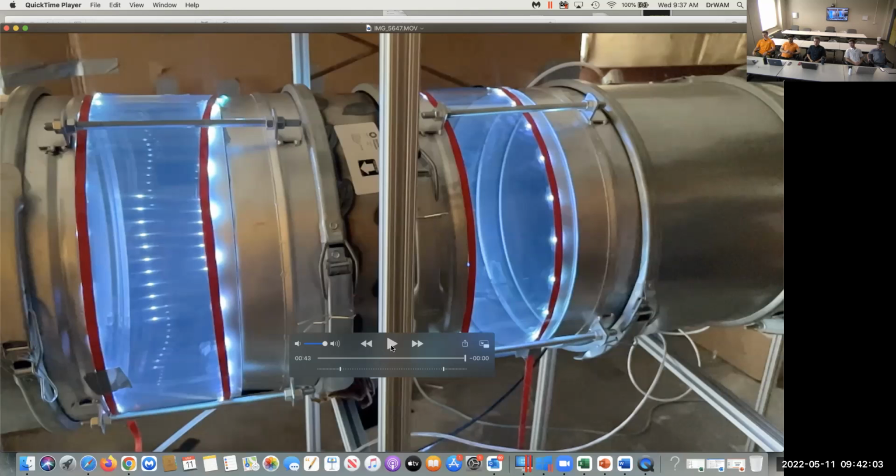And in that instance, am I getting a good mixing across the complete duct section, especially if that duct is 3 foot or 4 foot in diameter, which is typically what you have in these large air handlers. So the use of a blender makes, to me, good logical sense.